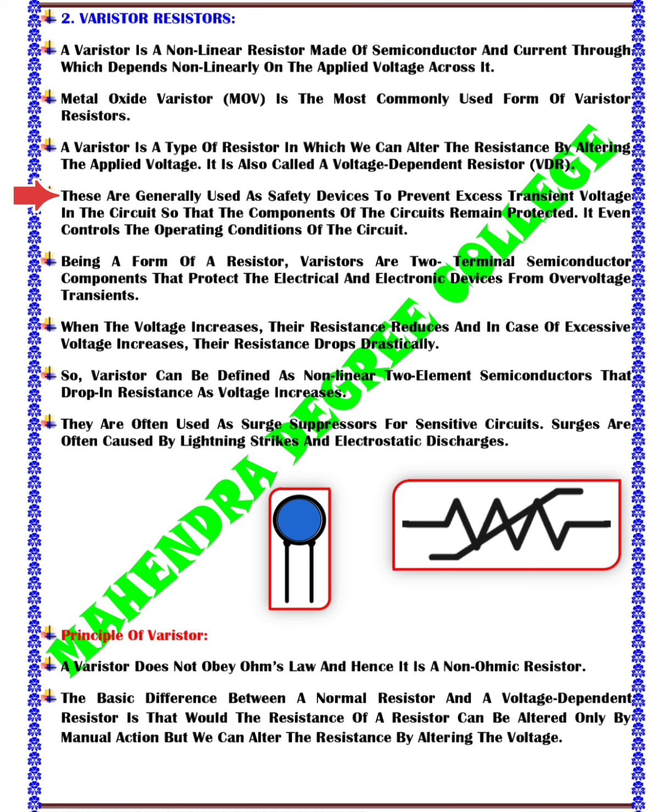A varistor is a voltage-limiting protection device. By using the nonlinear characteristics of a varistor, when an overvoltage occurs across a nonlinear varistor, the varistor can clamp the voltage to a relatively fixed value, thus protecting the back-end circuit.